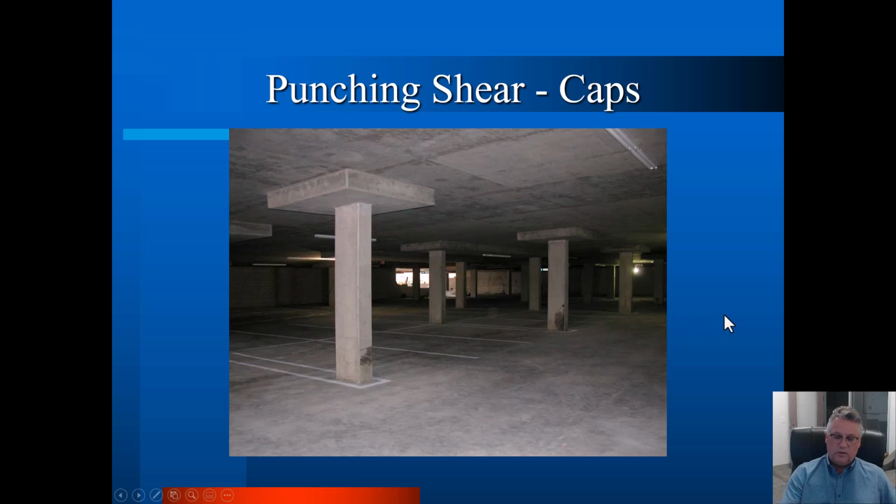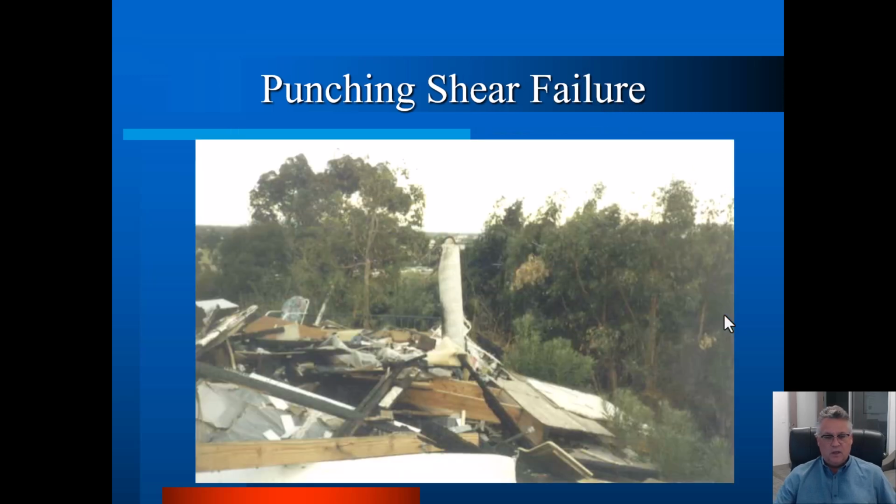But this was Northridge. This was a 3-story apartment building over one podium level, post-tension concrete. And had this not been post-tension concrete, this entire building would be sitting on the ground. This whole thing would have collapsed. The post-tensioning actually saved about 2/3 of this building. It stopped the domino progressive failure effect. So one end of the building, the